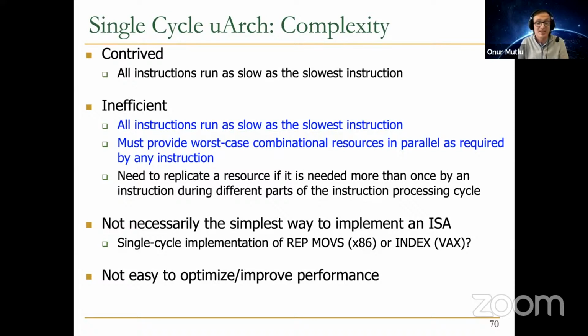That's just an example, but there's a counter register that determines how many you should copy. So I can actually copy 10 million bytes. And clearly there are 10 million times 2 memory accesses you need to do, times 2 in this case because it's a copy. Clearly, you don't want to be doing 10 million memory accesses in one cycle, right? In fact, how do you do that? I'm not even sure how you actually can build this. So it becomes contrived very quickly.